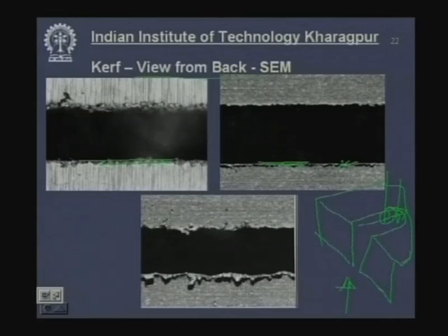Here not only is there burr formation, there is another important thing. What is it? See, there is variation. So much variation in the definition of the geometry. So, once again, what could be the reason? The energy content or the cutting ability was low in this one and was definitely much better in this. But these are issues which are to be kept in mind.